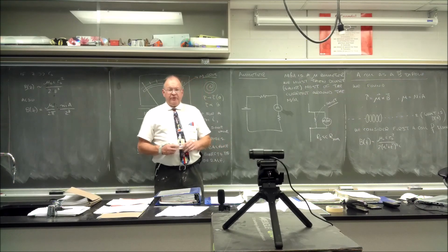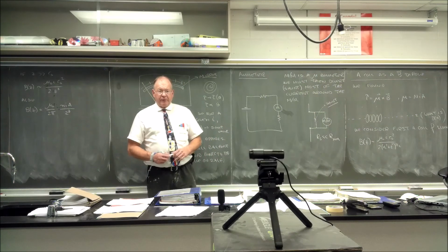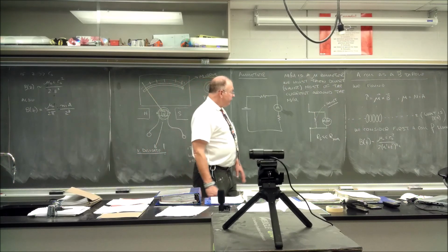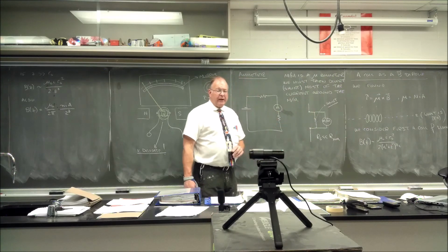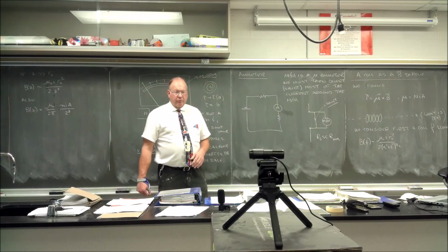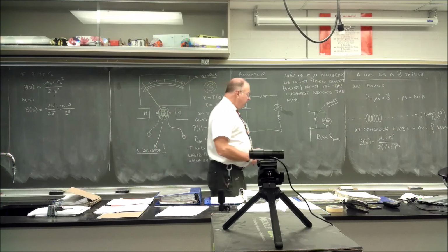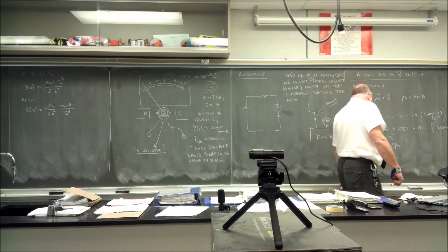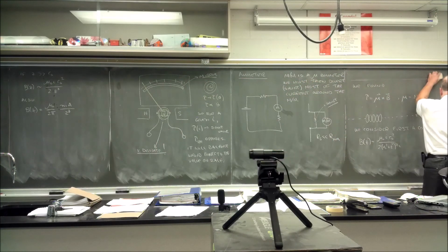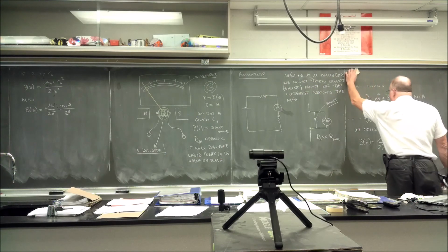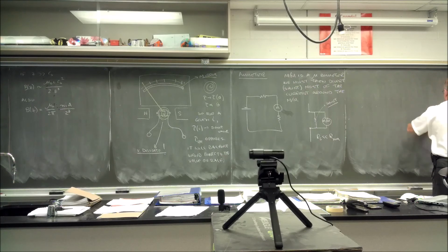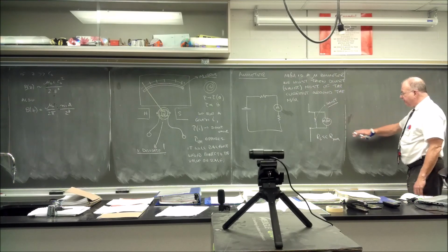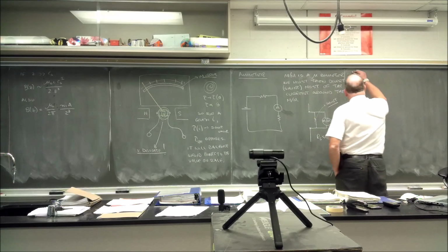Now, I've prohibited you from using the ammeter function because people don't know what they're doing and will choose the wrong one and it'll blow the fuse. We usually put a fuse in the meter to student-proof them as well, and we generally underfuse the meters as well, just to be safe. But most of the time, these meters are multiple, or what we call multimeters, which means they can measure not just current, but most people don't want to have an ammeter and a voltmeter and an ohm meter and all that kind of separate equipment. It's expensive. So for a voltmeter, it's the opposite.